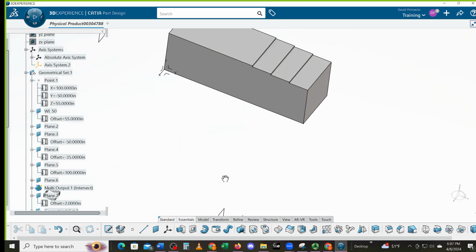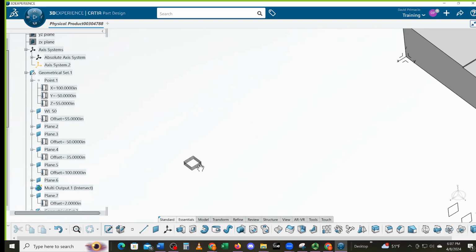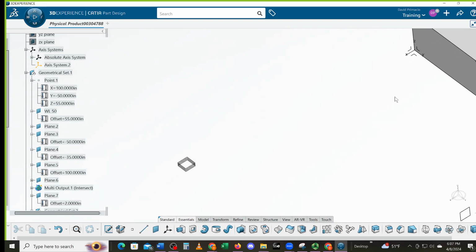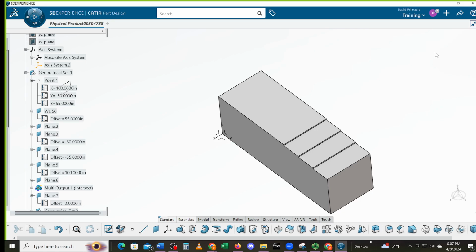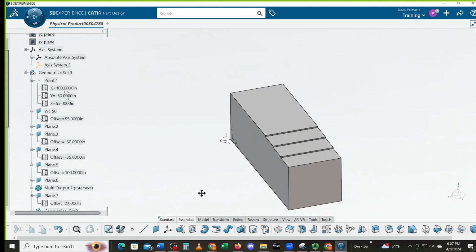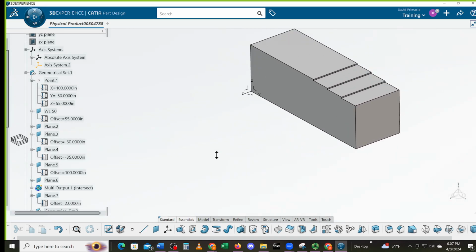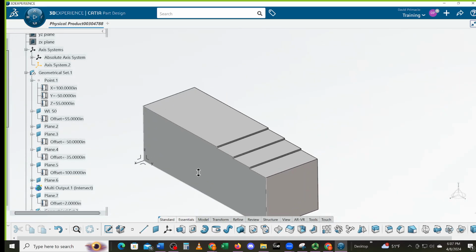You guys see how it's rotating really weird like this? Y'all know how to get around that, right? Yeah, middle click your center of rotation you want. So if I middle click right on the part, then when I rotate, it won't fly around so much. Okay, so that was my demo.